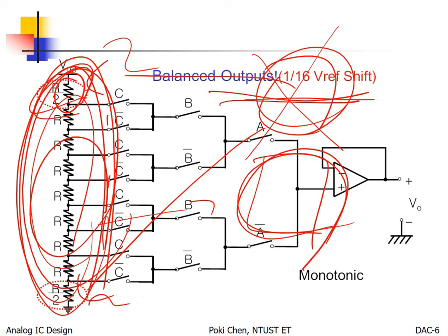Because you need to have at least common centroid layout, right? With common centroid layout, you can get the best result. Otherwise, all those nodes won't get correct voltages after division. So it is the other very hard issue for you to achieve.